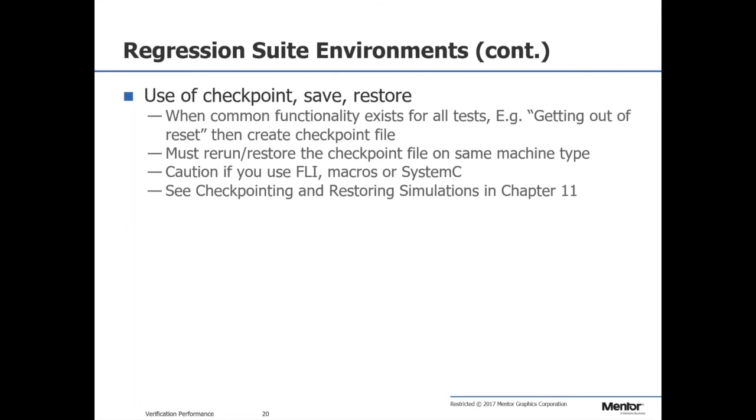If you have a PCIe bus, the first thing that happens is you come out of reset and the PCIe bus goes into this training phase. That training phase is negotiating speed, enumerating the buses, doing all this stuff. And that might take an hour of simulation time just to get the PCIe bus trained up.